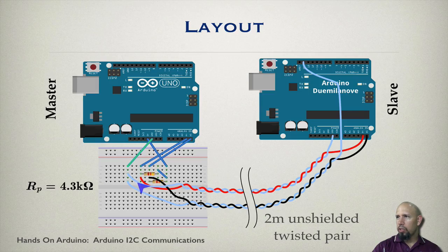When we do a twisted pair, we don't twist two data signals. The whole point of doing the twisting is to help prevent what's called electromagnetic interference, and electromagnetic interference often occurs when you have two signal wires right next to each other. So you definitely don't want to do a twisted pair with two signal wires. If you're going to use a twisted pair, you want to have the signal twisted with a ground wire. Having that ground wire is kind of like having a shield for that signal.